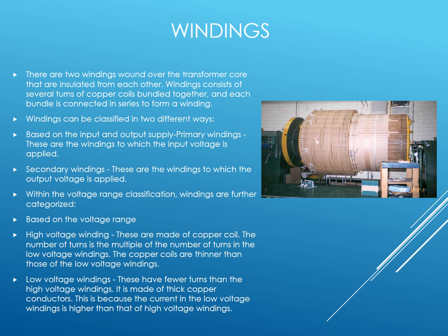Windings. Primary and secondary winding should be very close to each other to have mutual induction. There are two types of windings, cylindrical and sandwich type. Cylindrical coils are used in core type of transformers. These windings are mechanically strong.